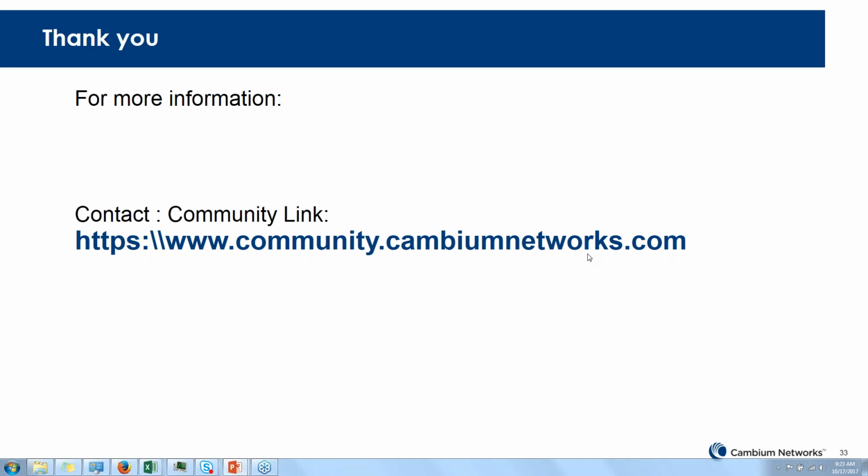Okay, I understand your question, Lionel. DSO is one good solution because of the radar and the DFS. A lot of customers are planning to use it in this format, where one channel is a DFS channel, which is the 5.4 band, and the other channel is a 5.8 or a 5.1, which is not subject to DFS. Even if you get hit by the DFS, you have to back off and that radio has to shut down for a certain amount of time till the radar detection is gone.